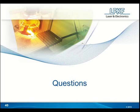Gotcha. Our next question comes from Michael, who wants to know, can you measure the depth? And I'm assuming he's referring to the depth of cuts. Yeah, the depth of cut on the machine itself, the UV laser, there are fiducial cameras for alignment, and there are very precise XY tables on many of the machines that are offered through LPKF or are in the industry. For depth of cut, there's equipment that can measure it. And when we do research and development applications, that's one of the key things, especially for microrobotic applications and microfluidics, where they want to know how deep they went.